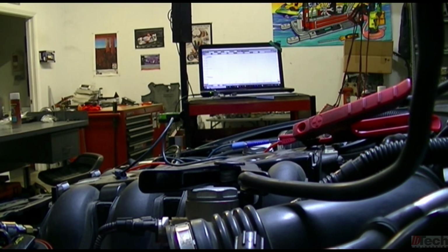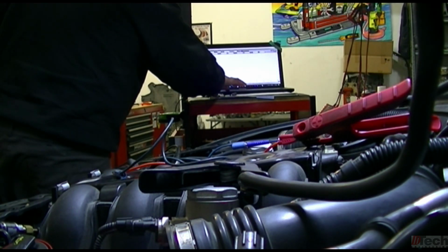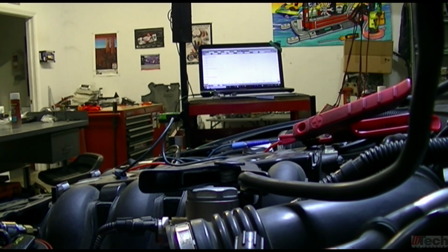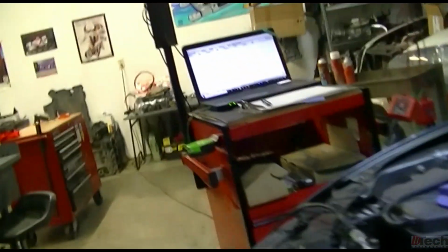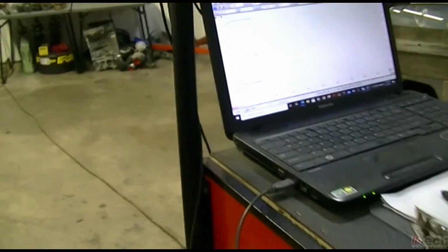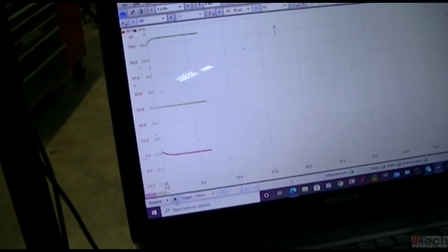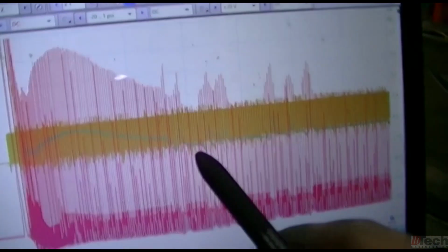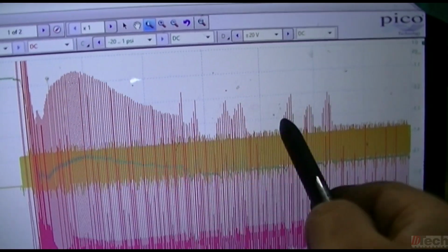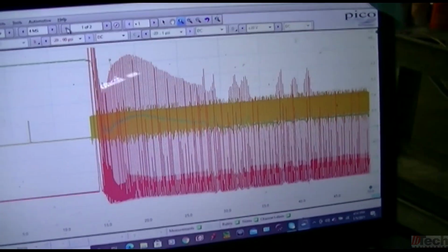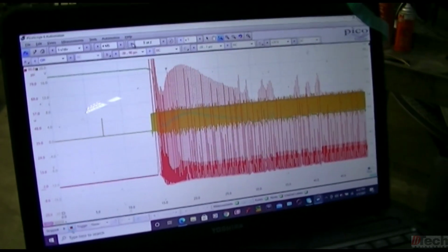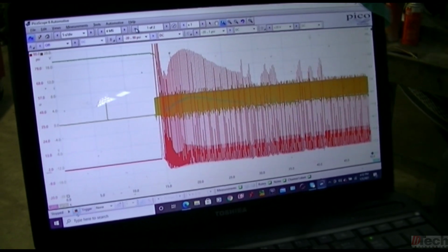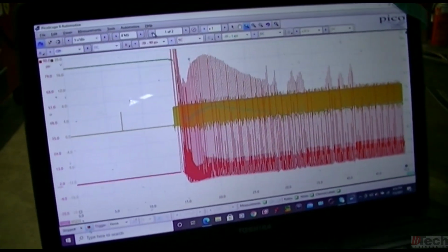Not sure if you can hear that idle change, but it did make a noise change, so something is working and happening. These high points are when I tap the solenoid. So I'll go ahead and save this, do the same for bank 2, and then analyze them both.